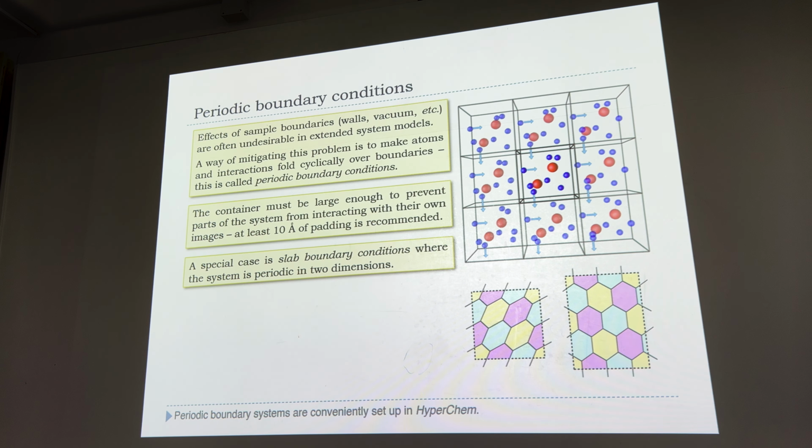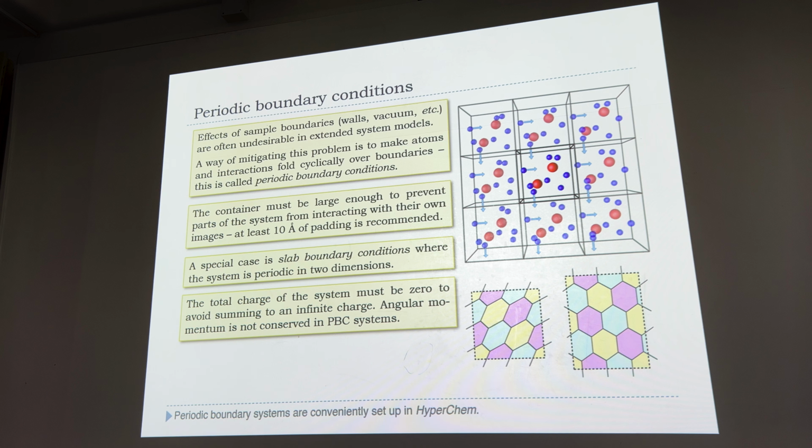If the atoms are not densely enough packed inside the unit cell, it makes sense to shrink the cell volume, which would, in that case, reduce the energy and be a legitimate optimization step. So you will discover that the programs that deal with periodic boundary conditions will also optimize your cell parameters in periodic calculations, not just the geometry of whatever sits within.